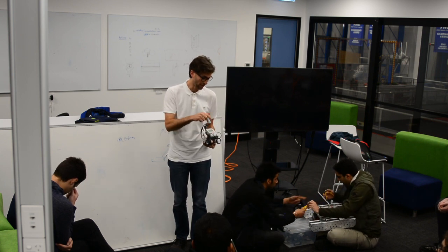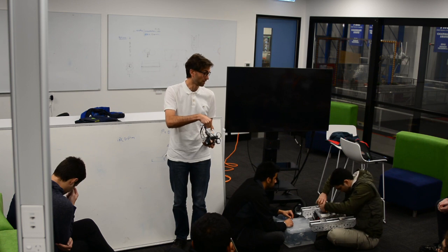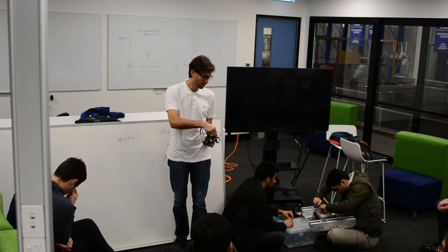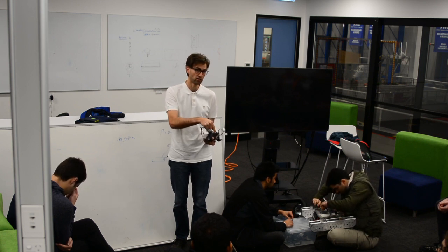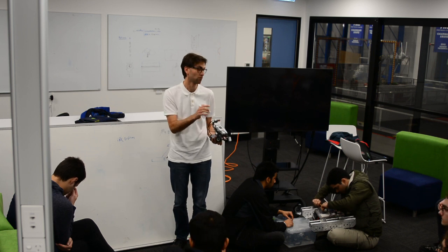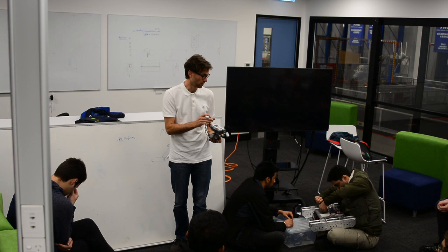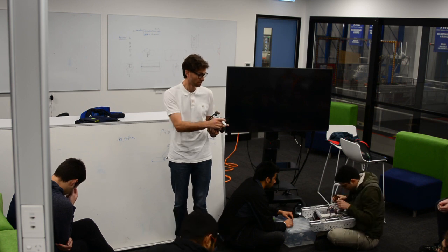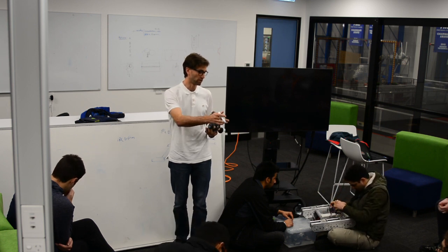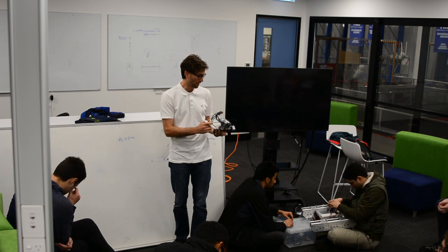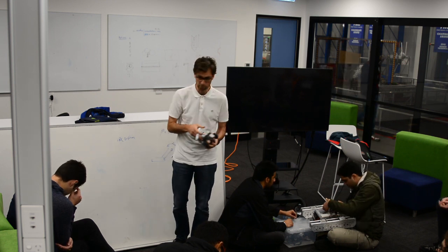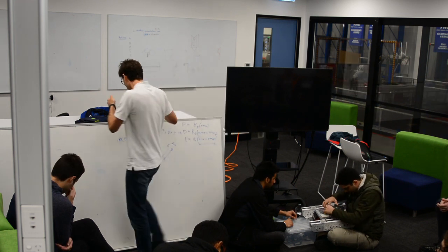And in fact, if you put the light sensor in the middle of the robot, it often doesn't work as well. So the position of this light sensor really matters in terms of the stability and the dynamics of this thing. I haven't done any math on it, but from experience I know that there's a sweet spot for where that sensor should be located.